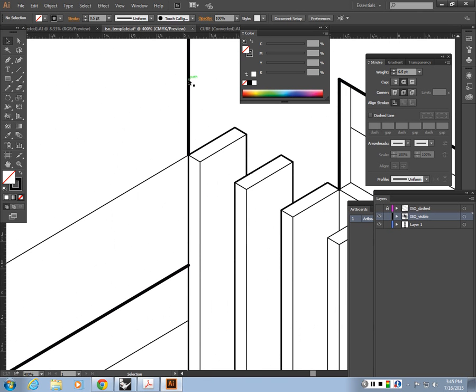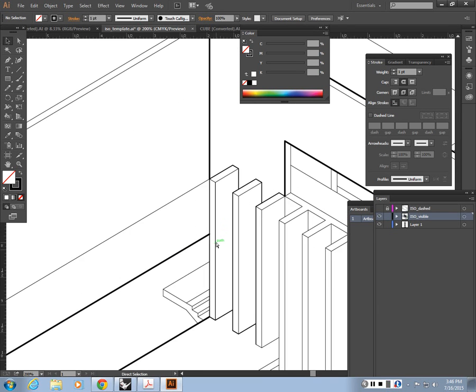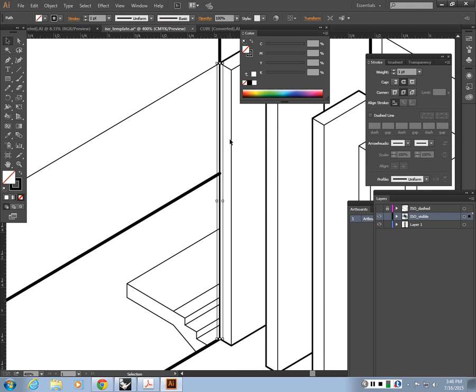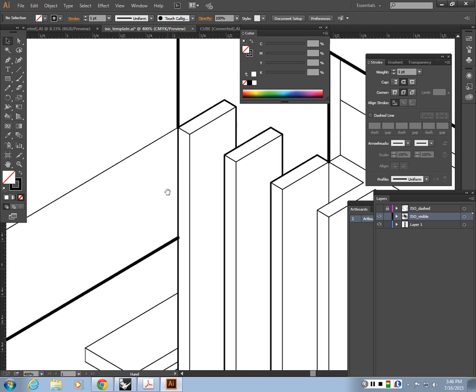So I'm bringing down 2, right? And this guy's a consistent line that is 1. But what I want is 2 here and then 1 all the way down, right? Because that's kind of an edge. I want it all to overlap with the wall behind. So I want to see 2 here and then 1 here. So I basically need to break this guy here. Okay? Does everybody see that? So that there's consistent line weight here.